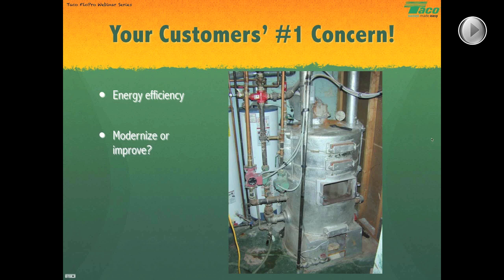Basically what you're looking at here is a question that most customers face. Do you want to modernize, meaning rip out what you have and start over again, or do you want to improve your system? It depends, really it depends. If there's an 8 or 9-year-old cast iron boiler, well, that thing's really maybe still a baby, all right? It's not something that you want to rip out and throw away in the name of getting a few more points of energy efficiency. Maybe there are things we can do to that boiler to make it as efficient as possible. Now, if it's a 35 or 40-year-old boiler that has been in constant need of repair pretty much every winter, and we're concerned that it's going to ultimately die in the middle of winter at the most inconvenient time, well, now there's an opportunity to modernize.